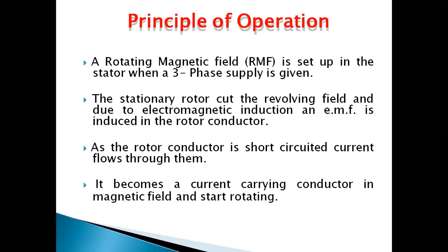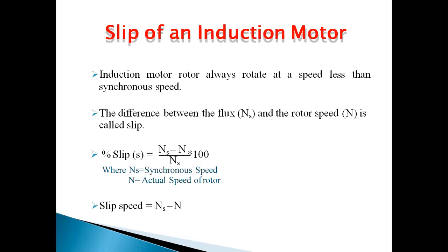So when we give the power supply, if the rotor cuts the field, EMF will get induced. Then it becomes a current carrying conductor in the magnetic field and the rotor will start to rotate. At that time, it converts the electrical energy into mechanical energy.